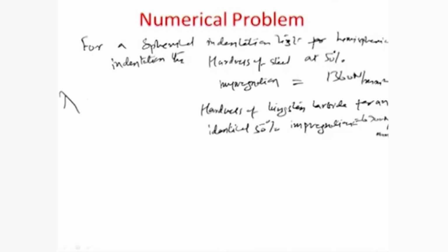So, obviously, the lambda value, which is nothing but the hardness ratio between the workpiece and the tool, as illustrated many times before, comes out to be about 5, right, 6900 by 1360. So, it is about 5. So, fine. So, we have the lambda value here.